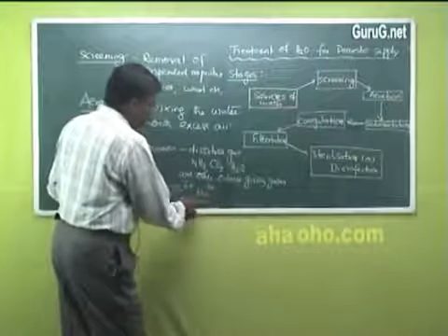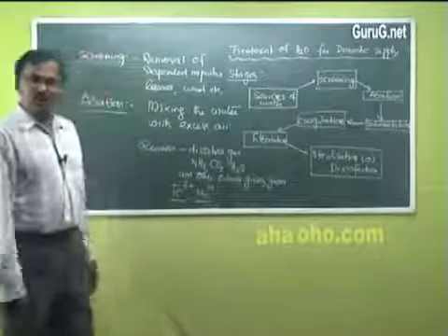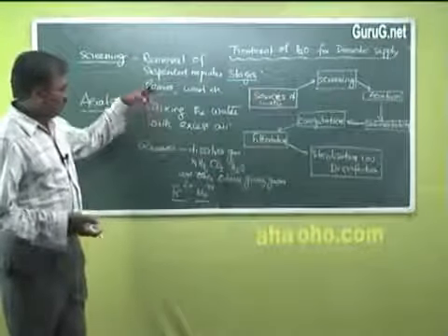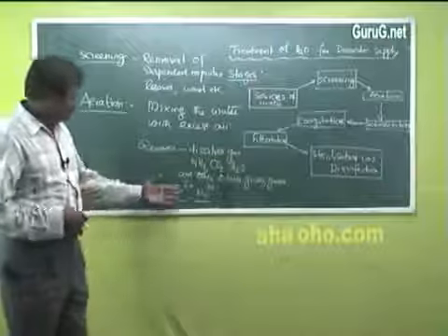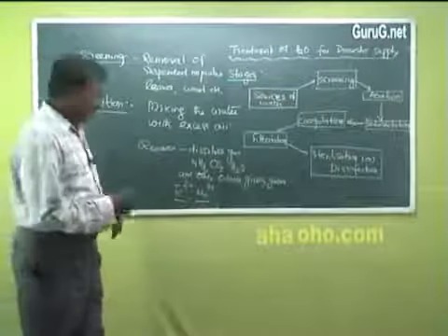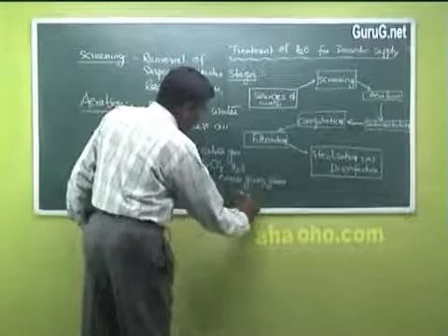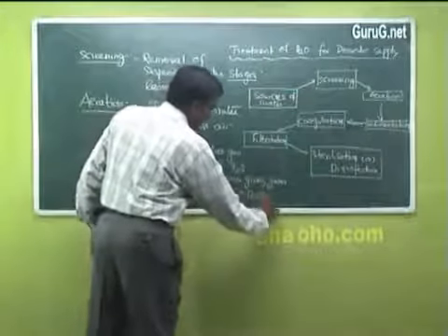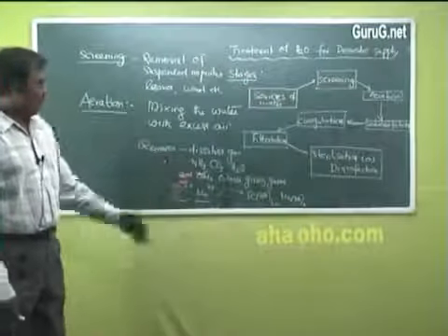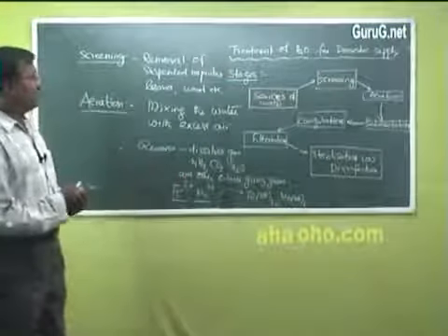These are in soluble form in the absence of excess air, whereas when we pass air, this Fe3+ and manganese salts are converted into the respective precipitates, so they can settle down. As the hydroxides are insoluble, they settle.